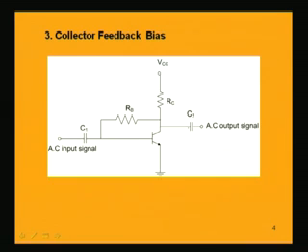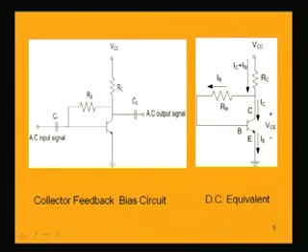The capacitances C1 and C2 are present to couple the signal effectively, and under DC conditions, when we only discuss the biasing scheme, these capacitances are open circuits, because under DC conditions a capacitance offers infinite capacitive reactance. So it is almost an open circuit. That is why, in the DC equivalent circuit for this whole amplifier, we are left with the circuit shown here.